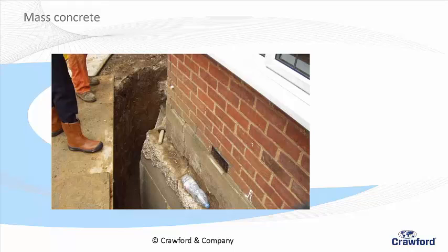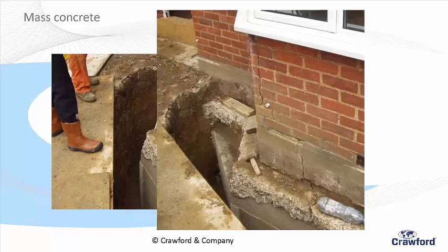Here it is in real life now, you can see it. So there's the original foundation, and funnily enough, you can see a crack there. And here's the new foundation. Can you see it looks very smooth? That's the print of my timber shutter against which it was cast. There's a better photo of it there. You can see the crack in the foundation as well. It's gone all the way through. And can you see these white bits here? These are my levelling points for how I level the building.